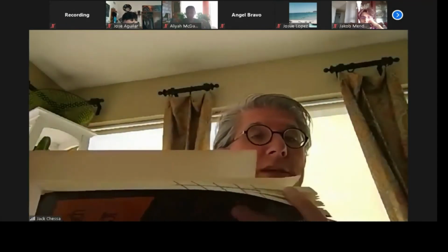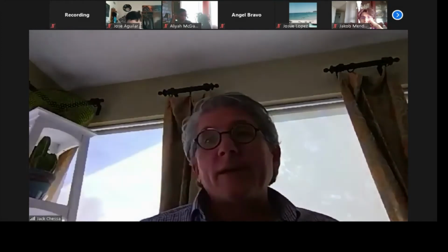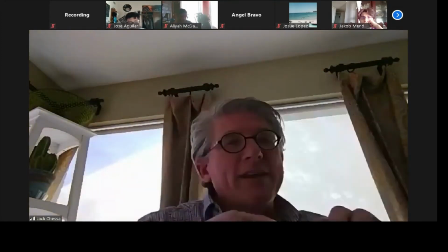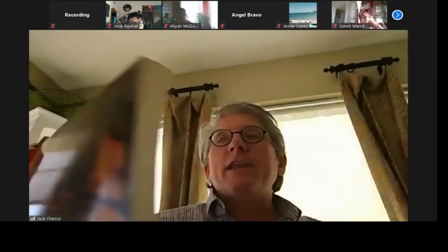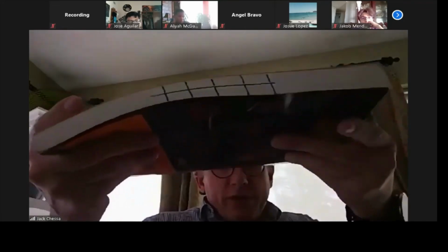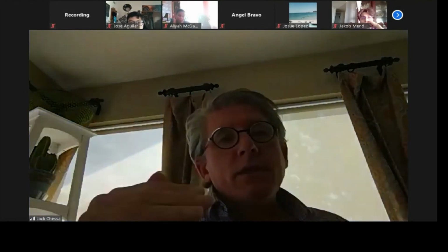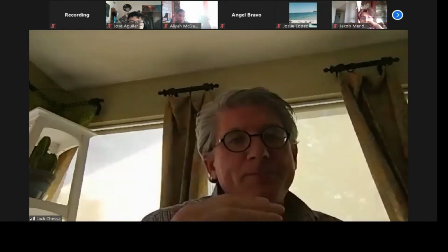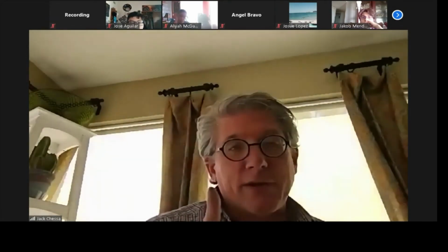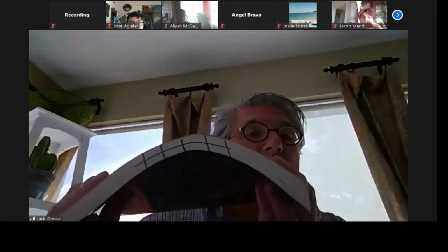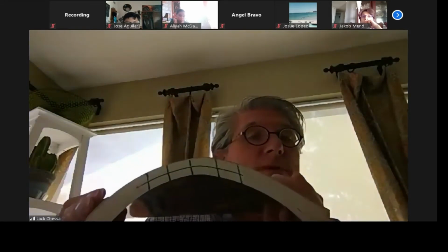The reason is that the pages are not glued together. If you have a regular beam, like if you try to bend your phone, it has much greater resistance because the material is integral or bonded across those. In here, the pages are not fixed, so when you bend it, they can freely slip relative to each other. They don't resist any shearing between the pages. So the book has no ability to resist the shear. That shear is what we call transverse shear. In the book, you can see it deform because there is no resistance to that transverse shear. That's what we're going to see.